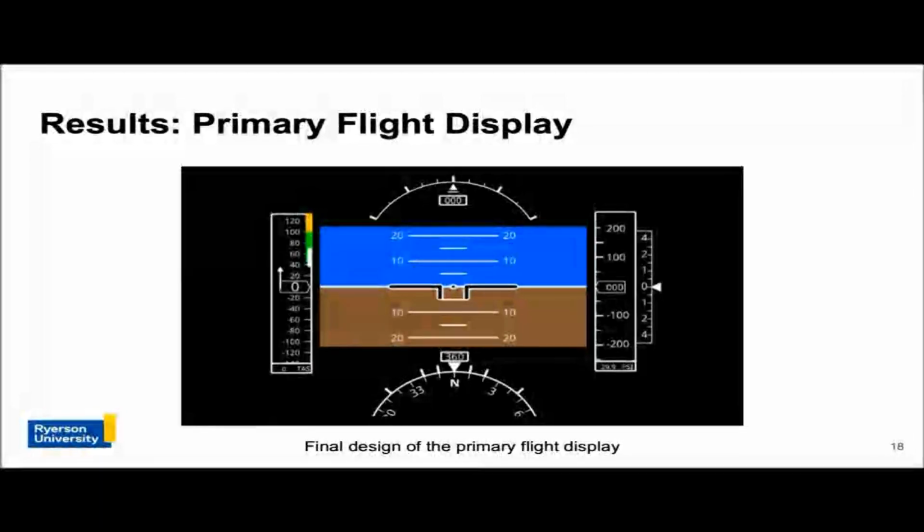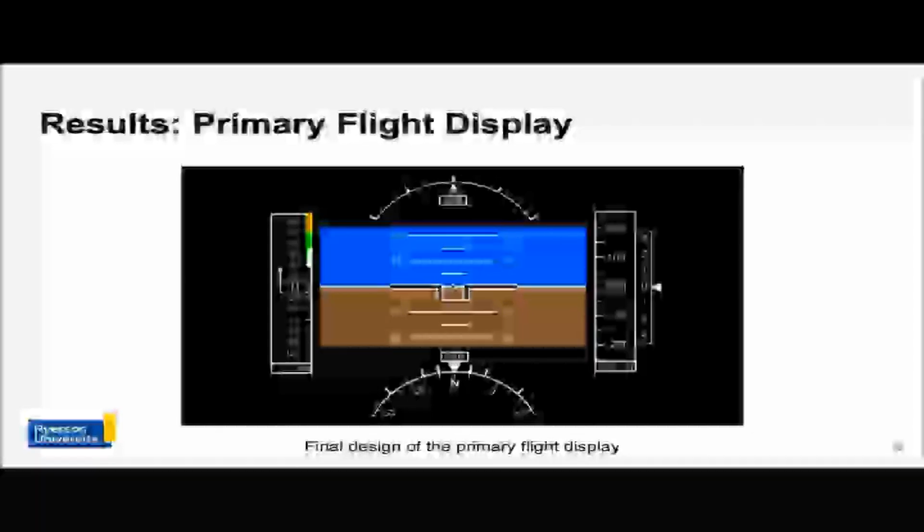The display has a connect value of 0.34, which is based on the assumption that the numeric readouts in text form will be used to gather data. However, since numeric readouts are less effective at communicating quick information, pointers and scales were also added on the display in order to give pilots a better understanding of trend changes.